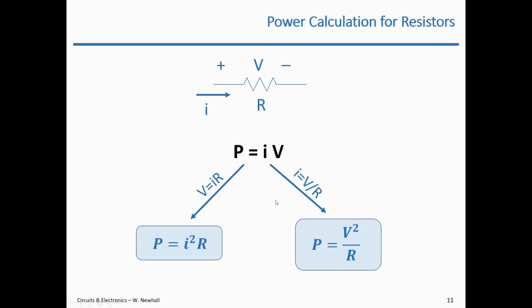From something really low, a few ohms, to something really high, a few k ohms. There's going to be a point where you get maximum power transfer, and we're going to talk about that. So for a given circuit, if I increase resistance, power might go up. For another circuit, if I increase resistance, power might go down. Okay, so we're going to take a look at that in a minute, but that's a good question. So keep that in mind until we talk about maximum power transfer.